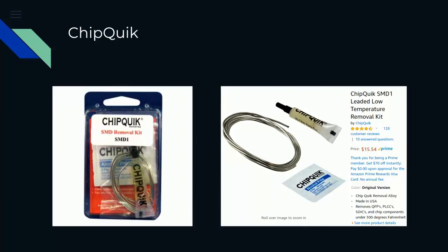Chip Quik, this is a chemical that is used to remove SMD, surface mount devices, from the board. So you can basically remove, for instance, a flash chip and try to hook it up to a flash header.